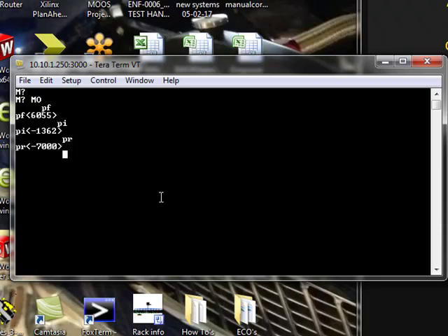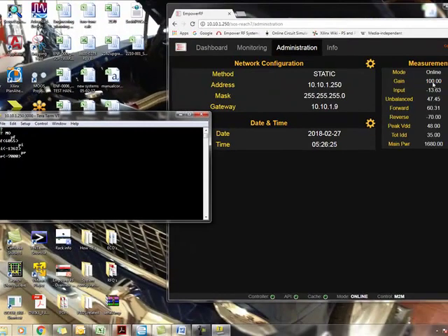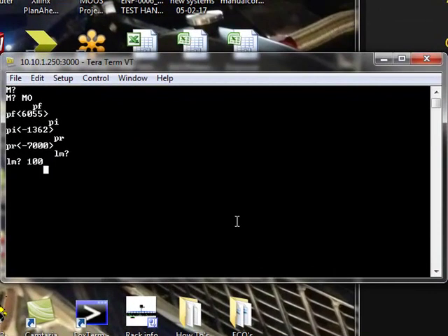To change the gain of the system, we use a command called LM. Just to see the current setting, which we're expecting to return 100%, we'll do LM query, and we can see the return is 100. The gain is set in units of percentage from 0 to 100%. 100% is maximum gain of the system, and 0% is the minimum gain for the system. There's about a 30 dB range between 0 and 100%.